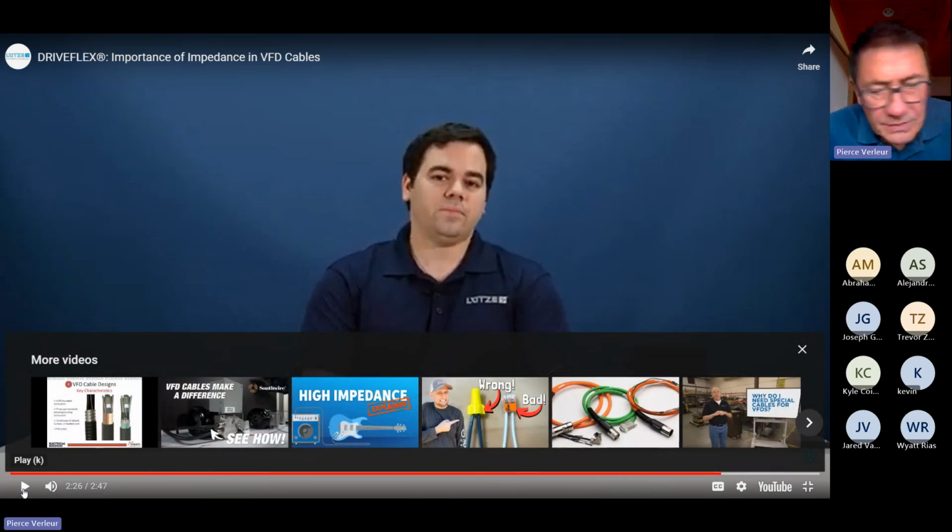Now, the first question you're going to get from your customer is, wait a minute, why do I want to use high impedance on a cable? The whole purpose of the cable is to be a low impedance pathway. Well, the answer to that is, if you have a circuit and you want to know the flow on that circuit, the point of most resistance or impedance is going to determine that flow. It's a serial situation. So you can have low impedance up to a point, and then you have high impedance like the motor winding, and that is going to limit the total flow.